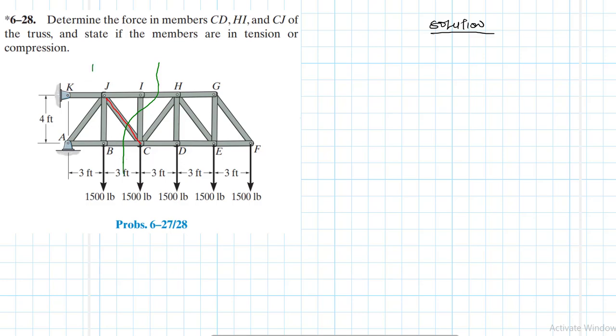I have the left hand side and the right hand side section. Great. But when we take this section, I always mention that when you are dealing with trusses, you need to isolate zero force members, right? So if I took this section, of course, in your mind, you're saying there are a lot of unknowns. We have a force in CI, which is unknown, but HI, we've already calculated it.